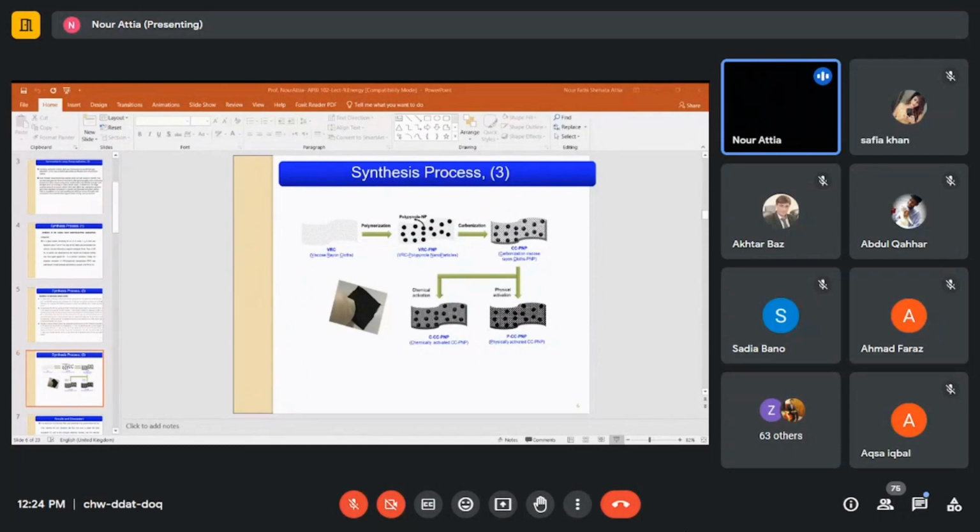The polypyrrole nanoparticles changed to porous carbon nanoparticles, and the size changed. It was 150, it became almost 100, but containing many pores. So we have a double structure right now. We have porous carbon nanoparticles decorated on the porous carbon textile, and this shows very interesting results. And even the carbon nanoparticles are rich with nitrogen, so we have double active sites existing in the porous material.